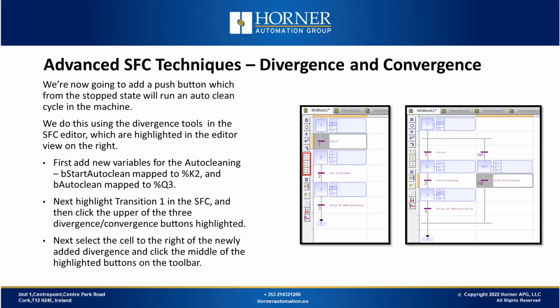The next feature we will look at as part of our advanced SFC techniques is divergence and convergence. Building on that application we were just working with, we're now going to add a push button which from the stop state will run an auto clean cycle in the machine. We'll do this using the divergence tools in the SFC editor, which are highlighted in the editor view on the right. So let's look at that process and then we'll go into a demonstration.